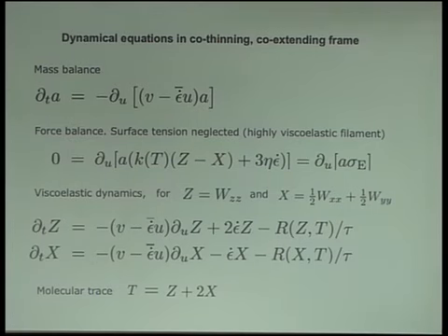We then have the viscoelastic constitutive equations that tell us about the dynamics of the viscoelastic stress components in the flow. So without flow, relaxing back to 0 and then being generated by a flow at a rate epsilon dot. And then we have convective terms here. So these are the equations that I'm going to use to study this problem throughout the rest of the talk.